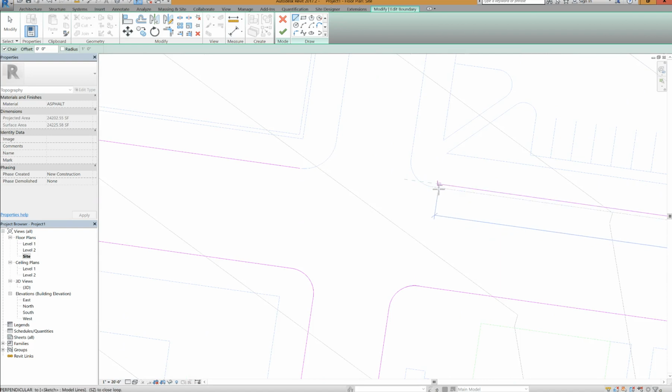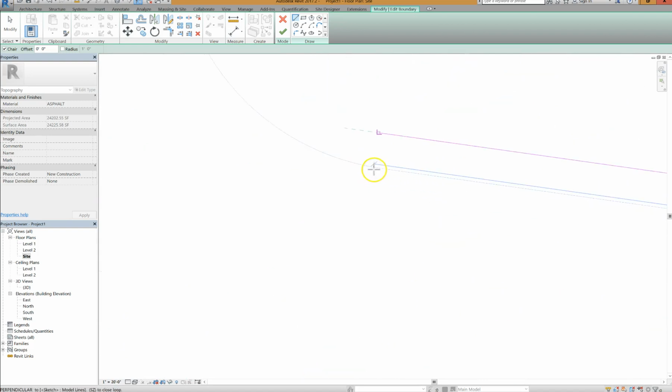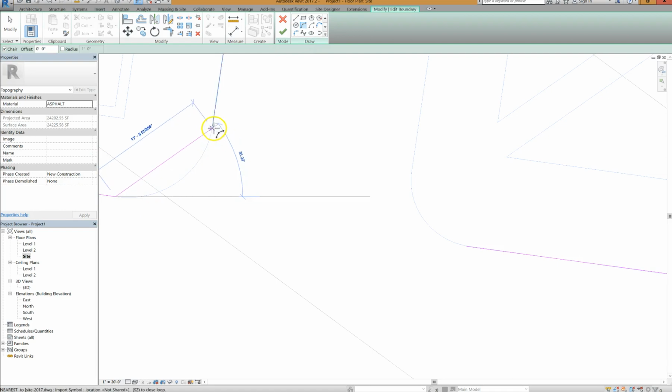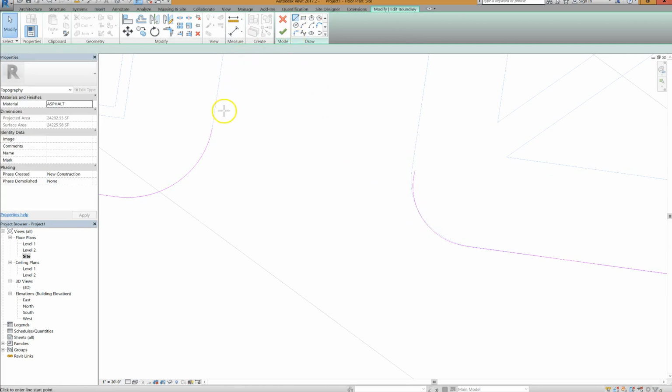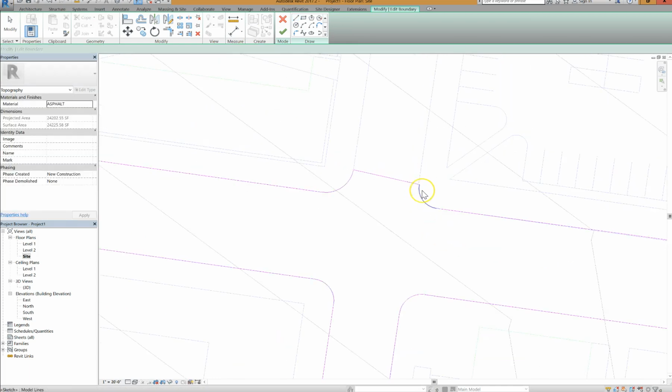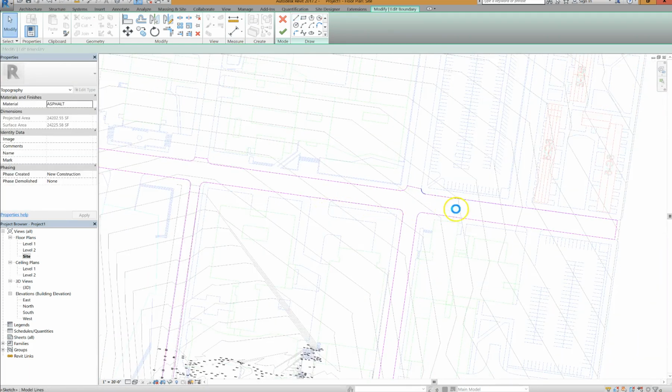So you draw this. Basically, what you're doing is you're drawing where the streets are in plan only, and then you can adjust your topography all you want, and the streets, the sidewalks, anything else that you create as a subregion will ride along with it. I'm not being perfect here because I'm not sure how perfect you're going to have to be with your site model about 1.5 blocks away from your project. That's really up to you.